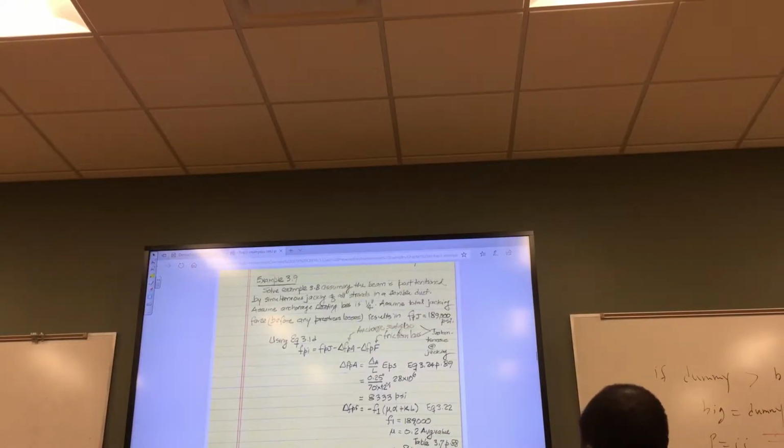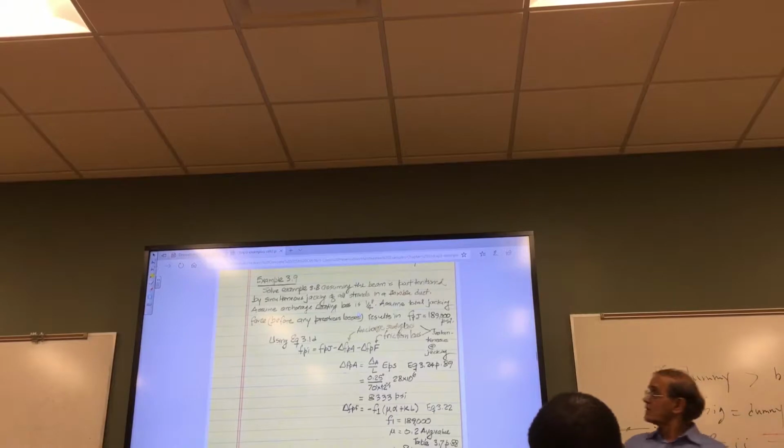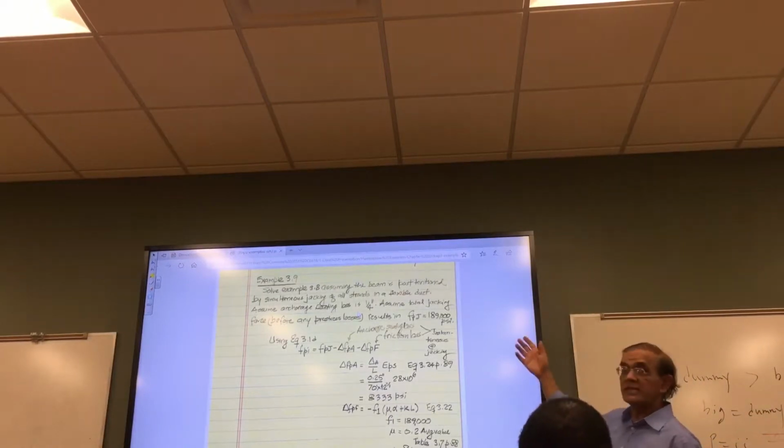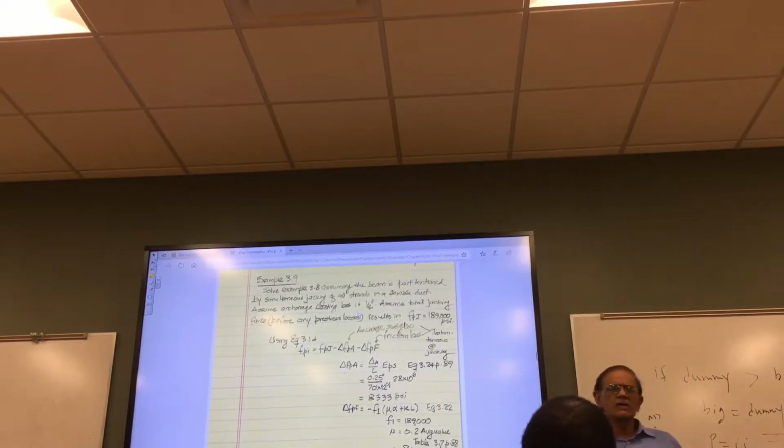And anchorage loss, where we need to assume the anchorage seating loss is 1/4 of an inch. In your assignment, it is 3/8 of an inch, so you can follow the steps basically. Slippage is 1/4 inch here versus 3/8 of an inch in the assignment. So accordingly, the strain will be different and the loss will be different. So it is very similar.